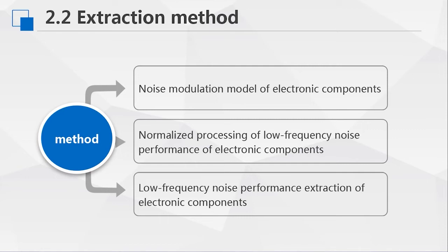According to the definition of the spectral correlation density function, it can be known that the spectral correlation density function of a signal represents the correlation of its spectrum on two different frequency components, and the weaker the correlation, the more characteristic the low-frequency noise performance at the cycle frequency.